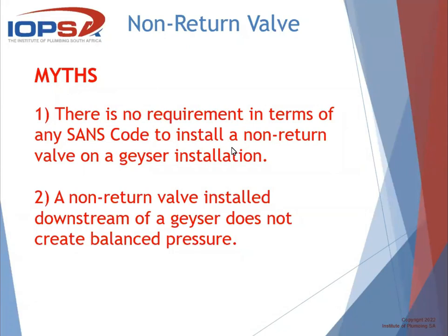Yeah, that's right. There's a question here from Colin. It says, I found that some check valves from a specific supplier vibrate and restrict the water flow. Yeah, you've got a spring with a plunger against a seat, and I suppose it's prone to all kinds of funny things, but strange that it should be vibrating to the extent where it should be a nuisance. But I've seen spring-loaded non-return valves on pumped loops, for example, perhaps a heat pump loop or whatever the case may be, where the spring pressure is too much for the pump to overcome.